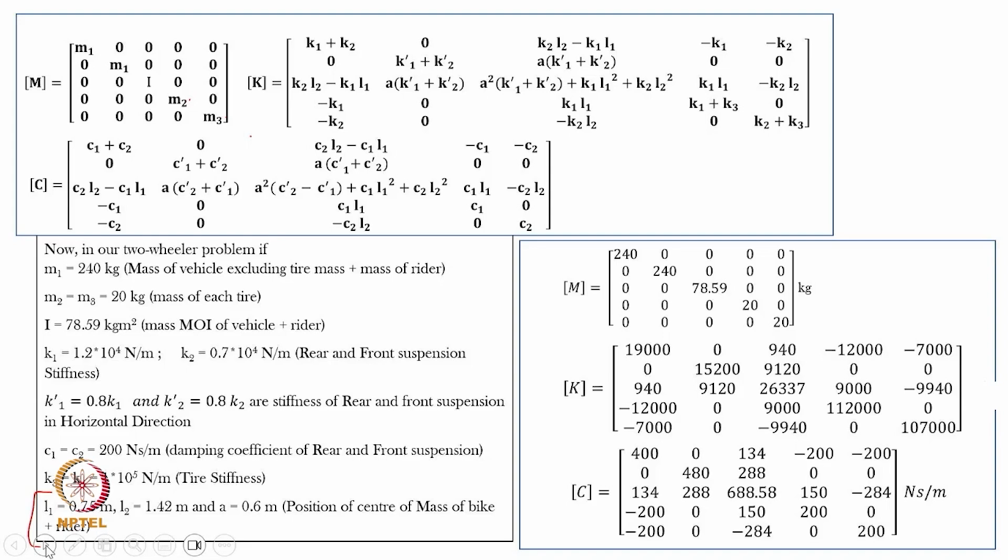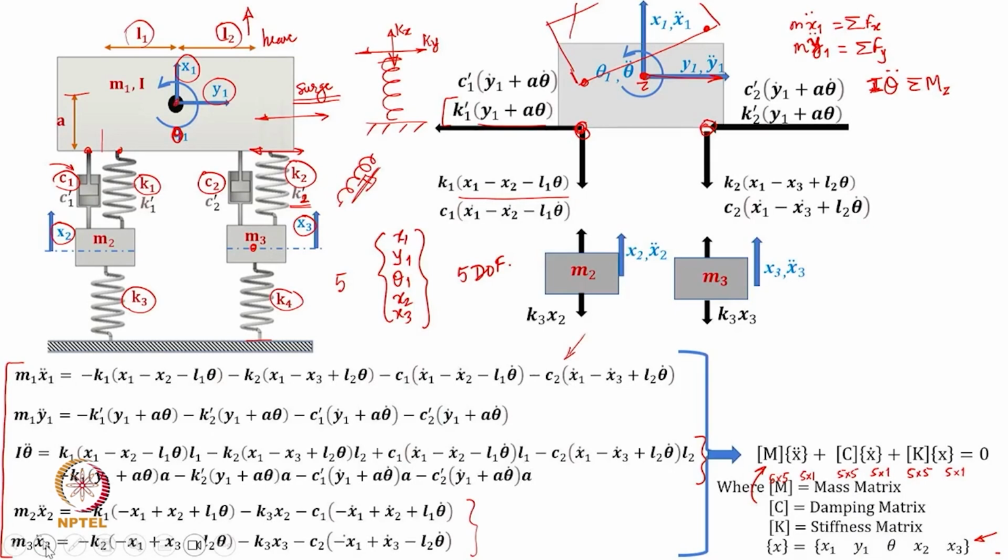Now, you can use any of the numerical methods that you might have learned in your engineering mathematics course to get the eigenvalues from these matrices, to get the natural frequency values. So, ultimately this is your governing equation of motion, and it needs to be solved for natural frequencies. Typically, when we looked at a simple single degree of freedom system, the free vibration governing equation of motion finally in a standard form turns out to be like this, where omega n is square root of k over m. So, for a single degree of freedom system, natural frequency straight away can be obtained.